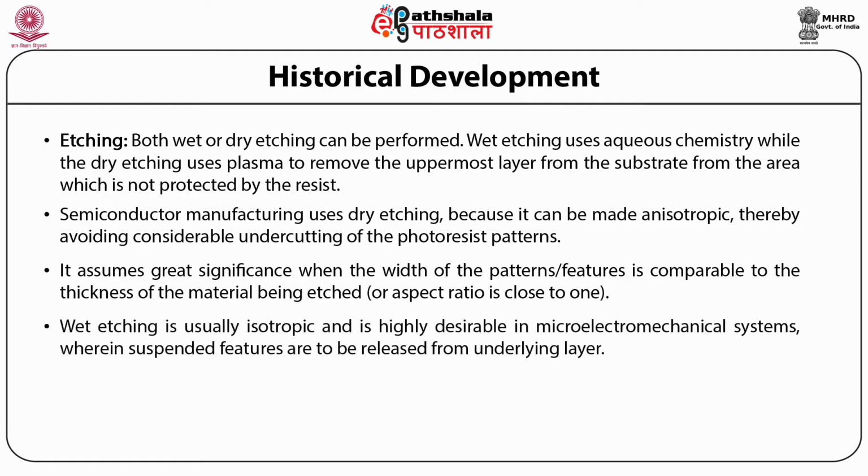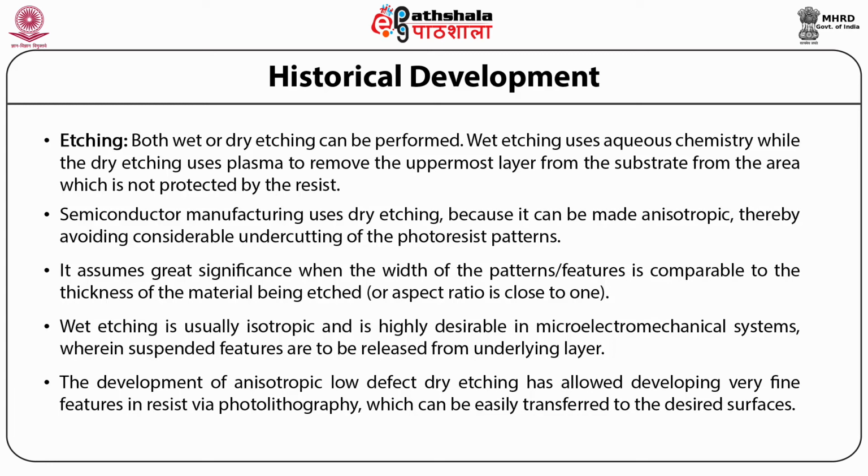Wet etching is usually isotropic and is highly desirable in microelectromechanical systems wherein suspended features are to be released from the underlying layer. The development of anisotropic dry etching has allowed developing very fine features in resist via photolithography, which can be easily transferred to the desired surface.